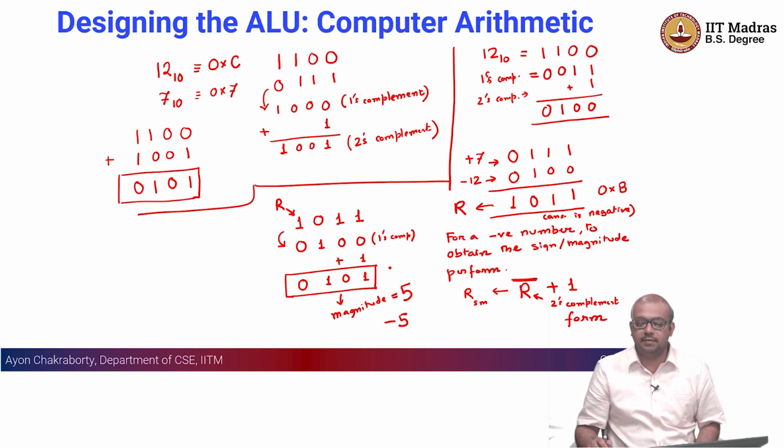If the system is very complex, with a lot of different components and a lot of intricate interactions between them, it is better to abstract some of these things in a hierarchical way. So, once you understand that the half adder is correct, from there you create a full adder, you understand this full adder is correct, and then you instantiate many of these full adders and create an ALU, rather than having an entirely flat circuit and repeating the task of creating multiple full adders, because in one of them you can make a mistake. Maybe you have made a mistake in the fifth full adder.